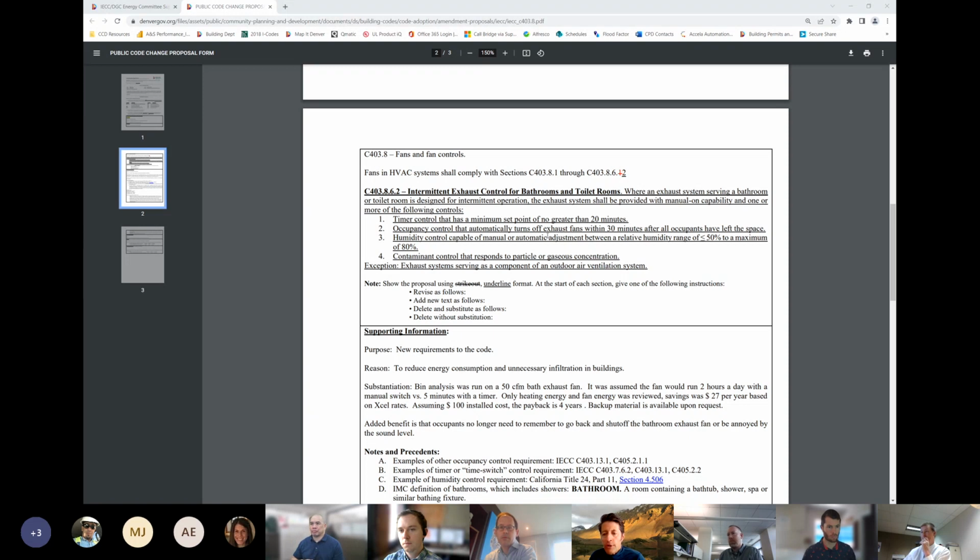On when an occupant enters and off when they exit, because that's what you'd really want. I think that's what's implied there. But I think there's probably situations where we don't want the fan on. So I think the manual on makes sense as well. We certainly may have a space where you want to go in and flick on the light, or the light comes on a sensor, but you don't need the fan running. So I do think there's an advantage, and that speaks to the earlier conversation regarding separate switching or separate sensors for these. In my opinion, providing the manual on capability is appropriate so that it's intentional to turn the fan on. Obviously people aren't working in the dark, so automatic lights make sense, but not necessarily needing a fan every time.